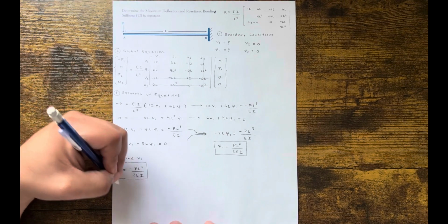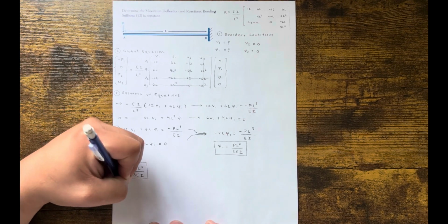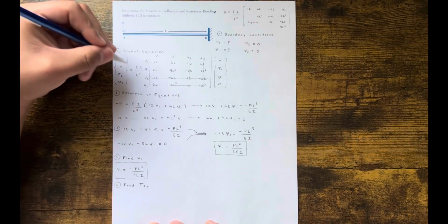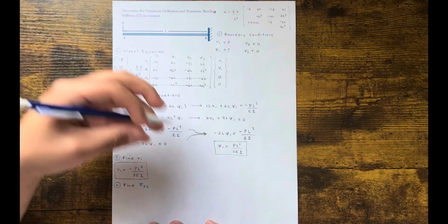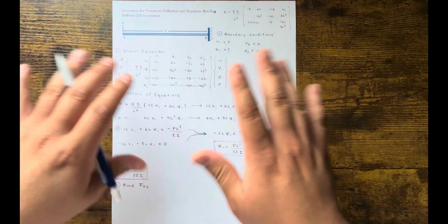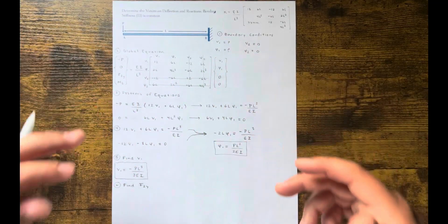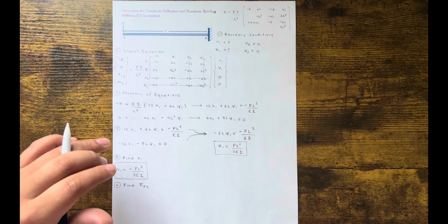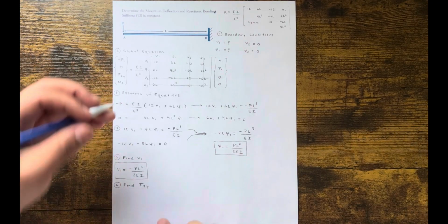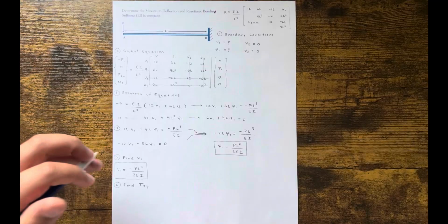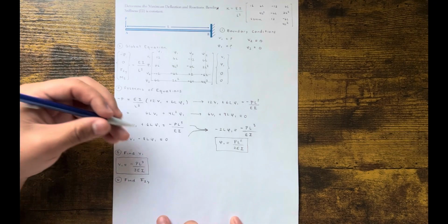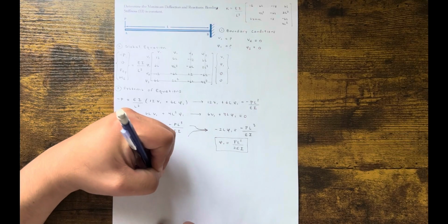So now I'm going to do the same thing. Step 2, find F2Y. There's a Y, right? Because we don't care about axial. The problems in this chapter only care about transversely loaded members. You only care about the bending moment and the rotation, transverse displacements, right? So we don't care about any x direction. So in this case, find F2Y, and then we're also going to find M2.